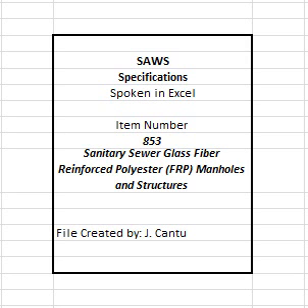9. Concrete encasements. Concrete encasement shall conform to specification item number 852, sanitary sewer manholes. Specifically, refer to standard detail drawing DD852 series. 10. Reinforcing steel. All reinforcing steel shall conform to provisions of specification item number 301, reinforcing steel. 11. Initial and secondary backfill material, refer to specification item number 804, excavation, trenching and backfill for all backfill requirements.